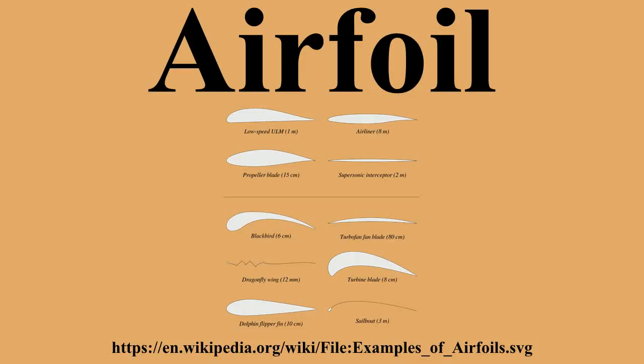Airfoil design is a major facet of aerodynamics. Various airfoils serve different flight regimes. Asymmetric airfoils can generate lift at zero angle of attack, while a symmetric airfoil may better suit frequent inverted flight, as in an aerobatic airplane. In the region of the ailerons and near a wingtip, a symmetric airfoil can be used to increase the range of angles of attack to avoid spin stall. Thus, a large range of angles can be used without boundary layer separation.